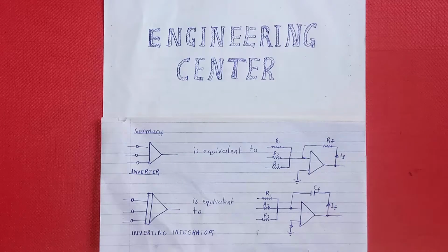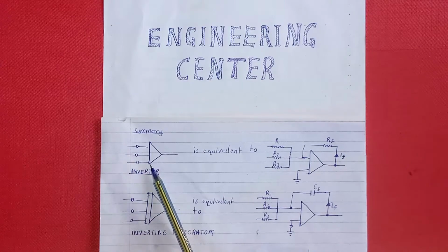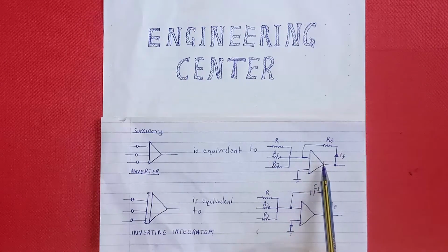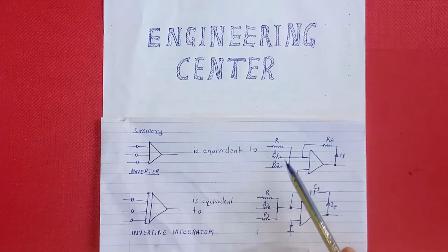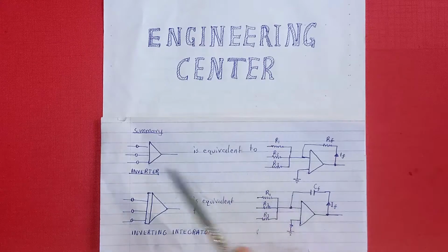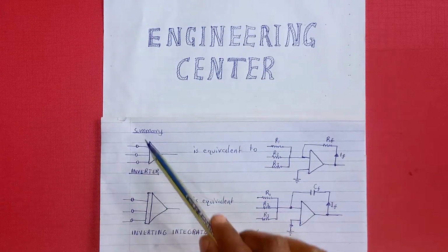In this video, I'll show you how to analyze simultaneous equations using operational amplifiers. Now, so as to avoid clumsiness of diagrams, I've decided to use this symbol here. This symbol is equivalent to this circuit, this inverter circuit, whereby this part here, called the summing point, is just this part over here, these branches.